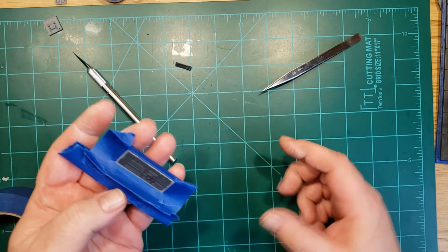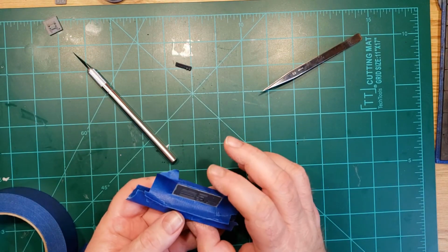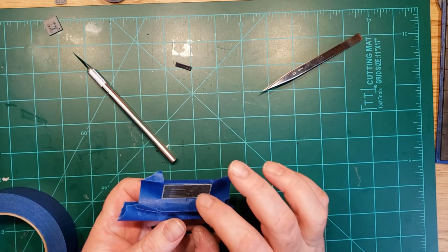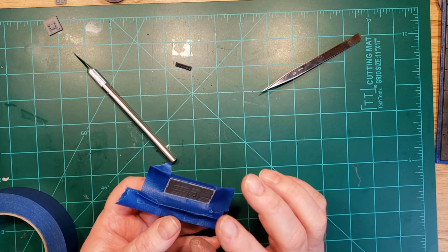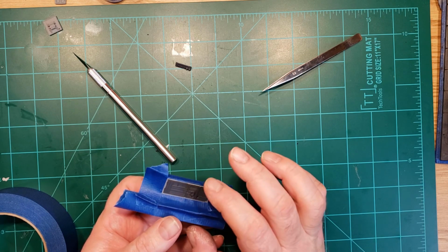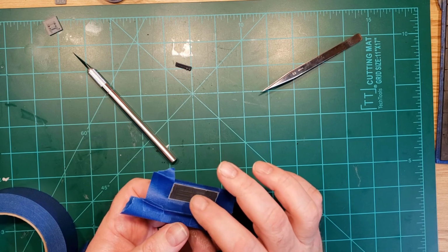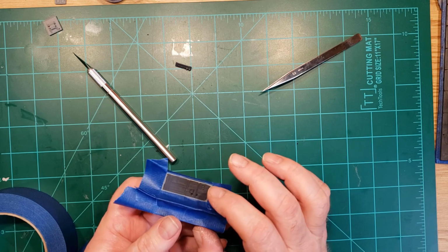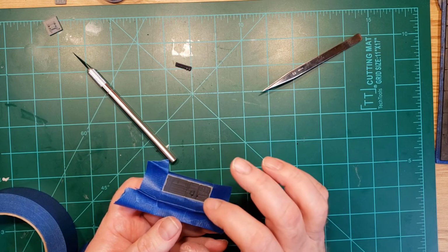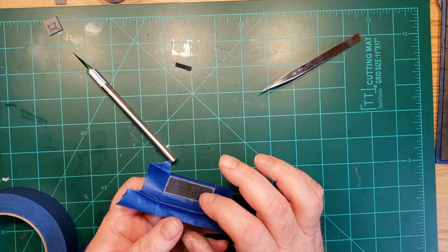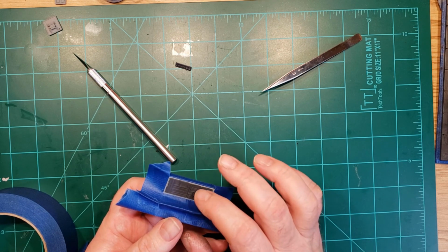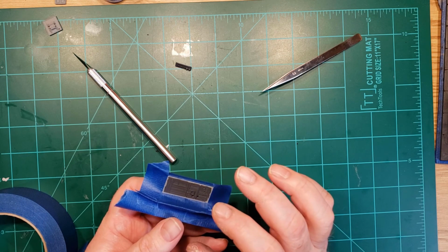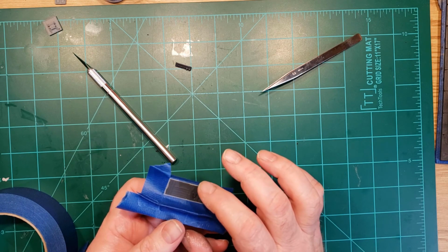So I'm going to go primer this, and I'll come back when I've got it primered and painted. I'm going to primer it tonight and let it sit overnight, because I'm using an enamel primer and acrylic paint. When you're doing that combination, you have to let the enamel cure completely. So I'll spray the enamel primer, and then I'll spray the acrylic paint tomorrow.